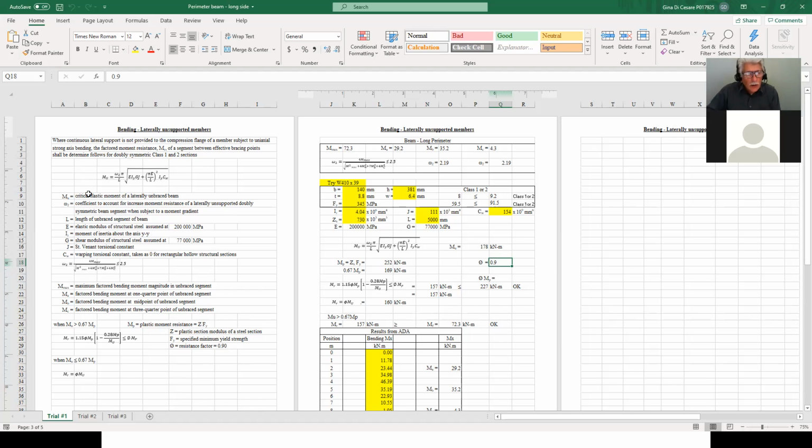That's all it is. So here it is, and then again, this Mu value here is calculated from this, okay, and the omega value is calculated up here in my spreadsheet. Now, depending on the value of Mu versus the value of MP, what they call the plastic moment. In other words, that is the most you can get out of a cross section.